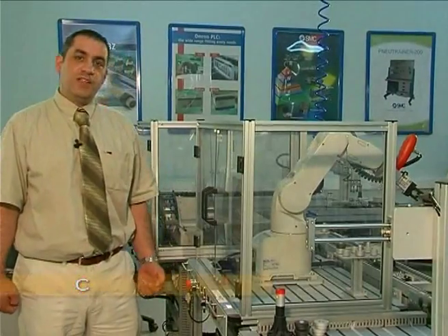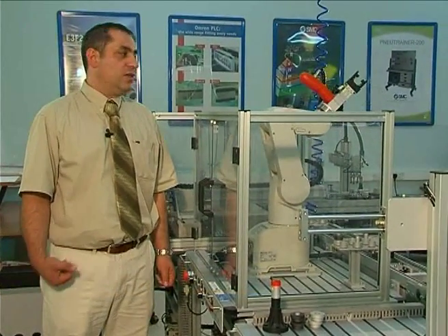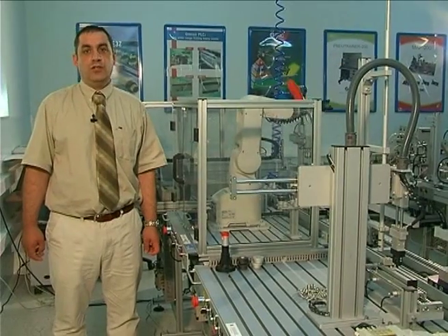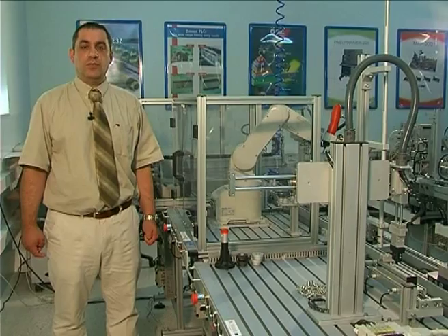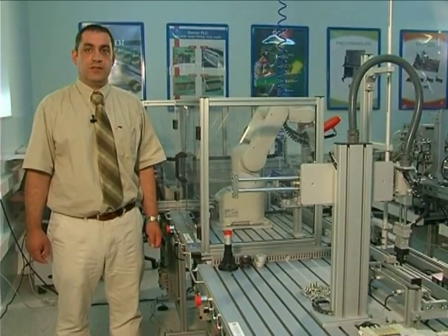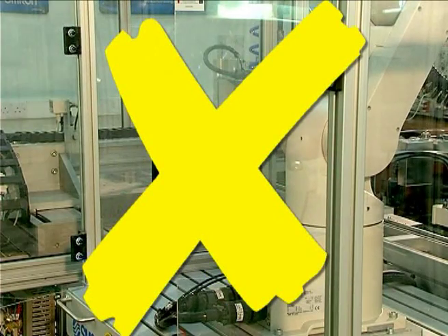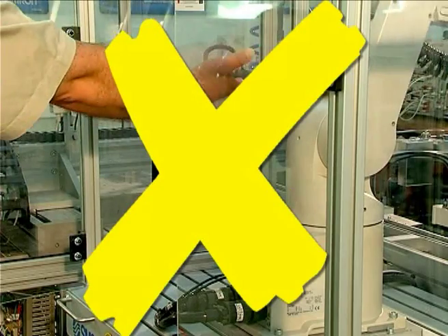Before starting this presentation on robot programming, we must emphasize the importance of the safety rules that apply in robot applications. The following safety rules must always be followed. Students must keep in mind that this equipment is dangerous due to its rapid movement and forces involved. Therefore, the following safety regulations must be clearly stated and understood by the user before starting any task. Never enter the workspace when servo power is on.